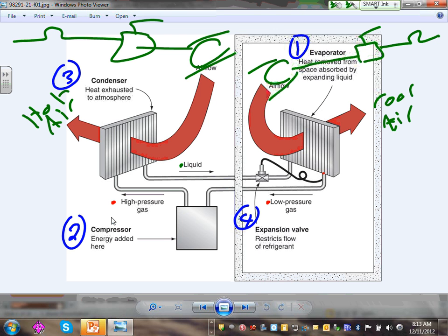The process of removing hot air from the room: if you remove hot air from the room, Jeff, you basically cool the room. Make sense? Any questions, guys, about where we interface? Another interface is the compressor. What do you think the compressor is going to need? A disconnect and overcurrent protection device. All these points are our interface with this mechanical system.